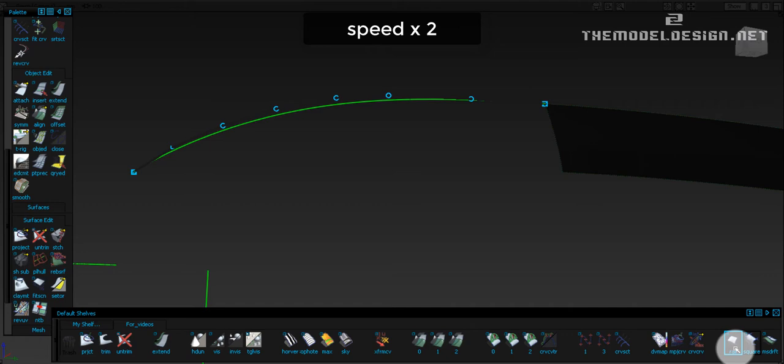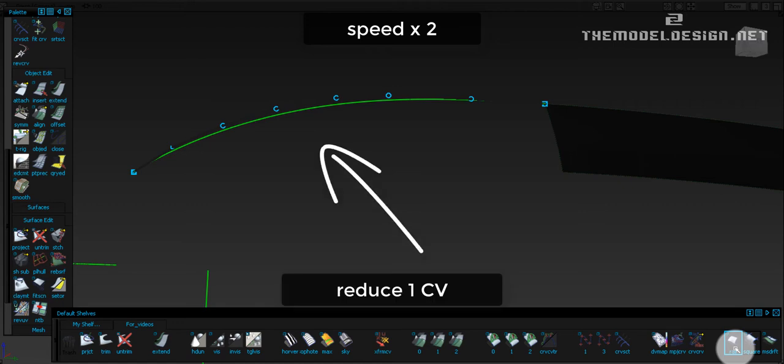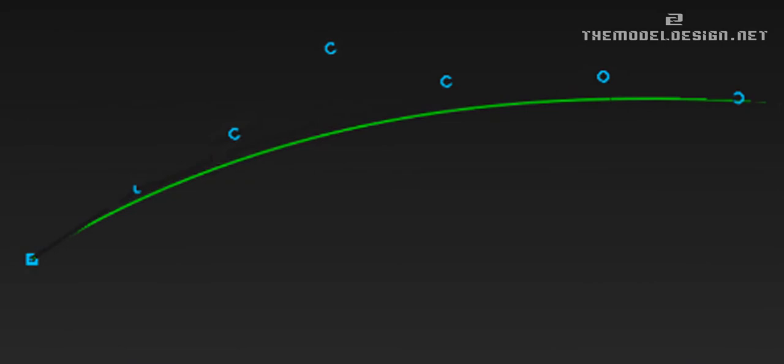A typical workflow in the automotive industry around this corner blend would be to make this patch 6 degrees. The additional 6th degree would shoot out very unnaturally. But I prefer keeping everything more natural with 7 degrees.